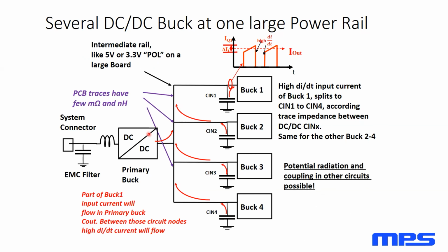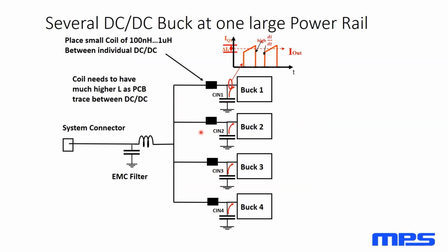We can also think about this. We've now inserted an off battery supply, and we're going to point of load power supplies. So we've got a 5 volt or 3.3 rail, and we're supplying 1 volt, 1.1, 1.8, different rails we might need in a larger system. We can still have this sort of phenomenon where the bucks are providing energy back to one another and having currents flow in directions we don't want them to. So the way we can address that is to add some impedance in between each of these. Now, knowing that electrons are lazy, because we have some resistance going back this way.